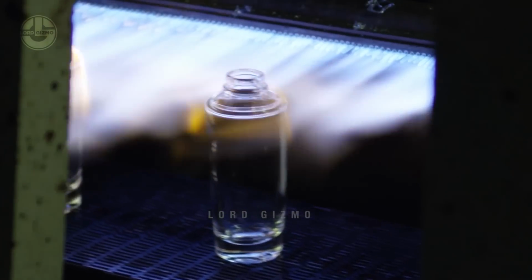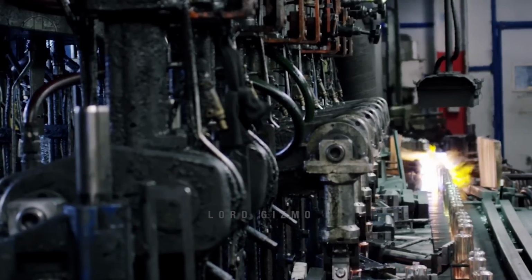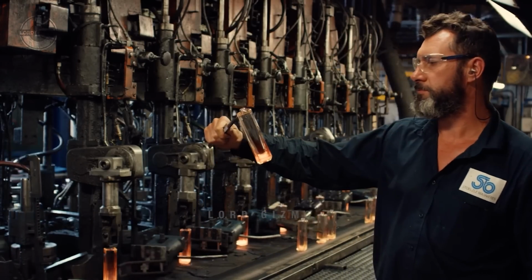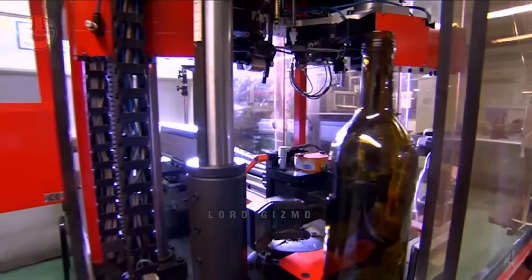Glass bottles are not done yet. They need to be annealed. For this purpose, they are slowly reheated and likewise gradually cooled down. In the next stage, every glass bottle is inspected using an automatic check system or by experienced employees to ensure the quality of the final product.